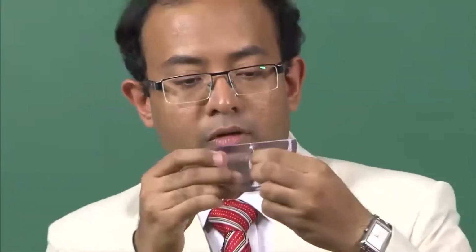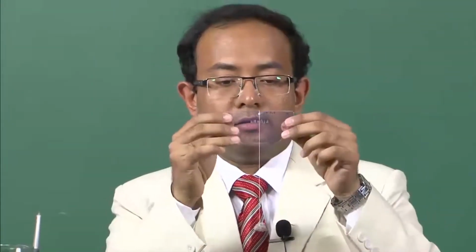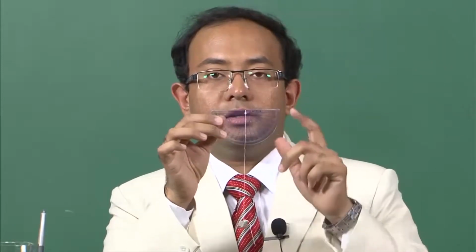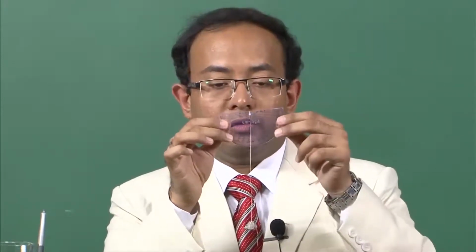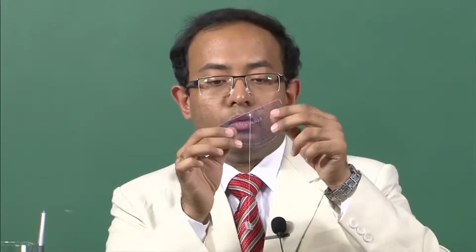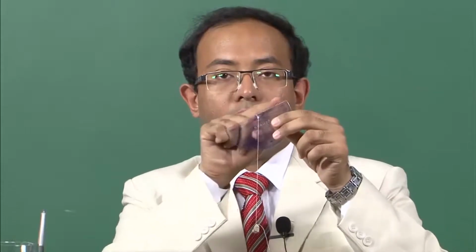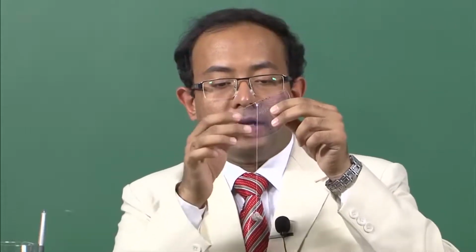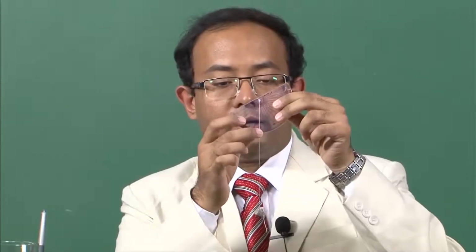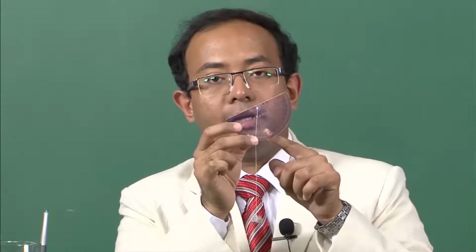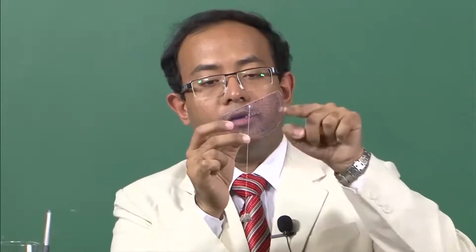So, now if I hold it like this, you can see that this angle is coming out to be 90 degrees. Now, if you want to measure the elevation of some point, when we turn it like this, the angle that we are interested in measuring is this angle. So, how can we reach that angle? Well, we can directly measure that this point now says 120 degrees. So, we can measure 120 degrees minus 90 degrees, which would give us this angle.